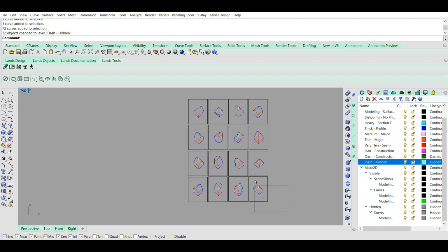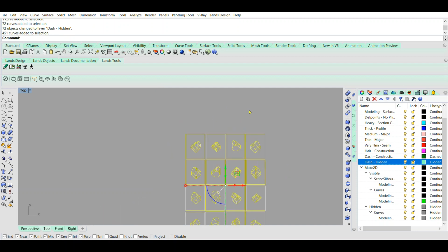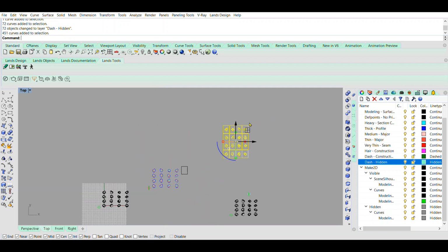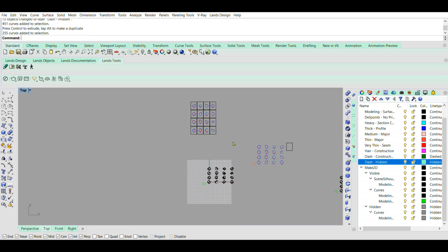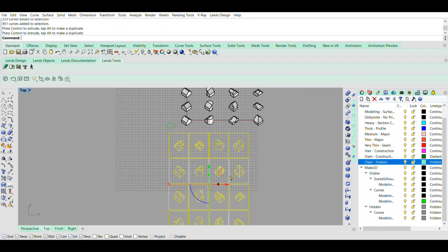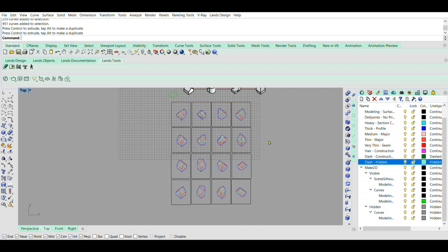developed surface drawings. So whenever you're ready to export these and you have these scaled, you'll select whatever you had ready to go on your artboards, and then you'll want to move these closer to the origin. And then you'll go to File and Export, and then you'll export those as a DXF with the 2004-2007 polygon lines, and then place those into your artboards in your Illustrator file. And that is module 1.